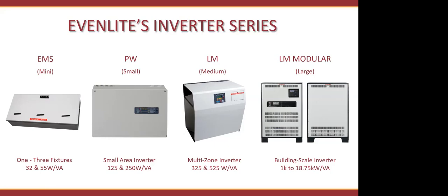Do I recommend specifying up to 250 watts on a 250 watt inverter? And the answer is no. And I would not recommend doing that on any inverter from any manufacturer. The reason why is there's multiple reasons for this. So one reason is that when we're talking about fixtures, fixture manufacturers generally are looking to build their fixtures as cheap as they possibly can while maintaining quality.